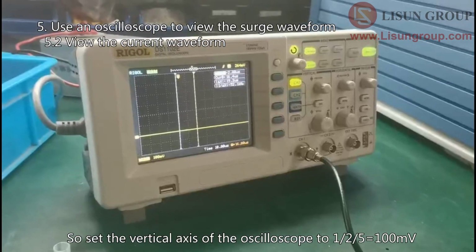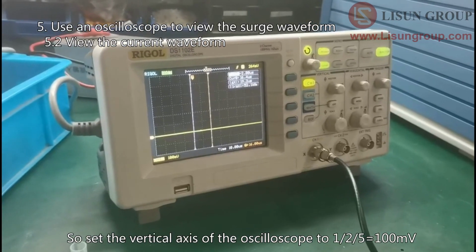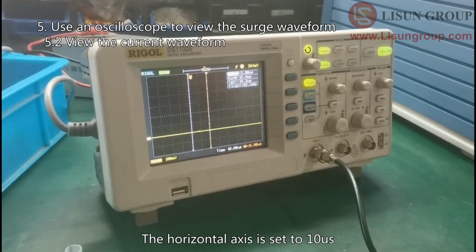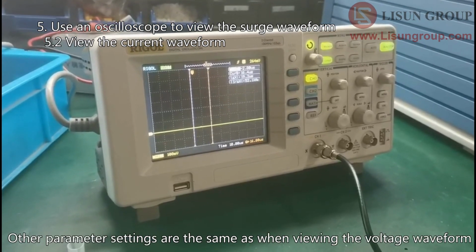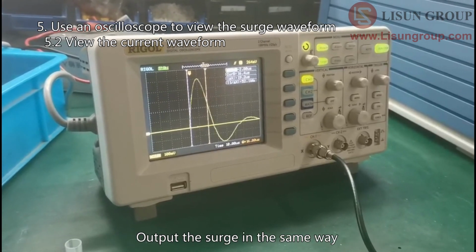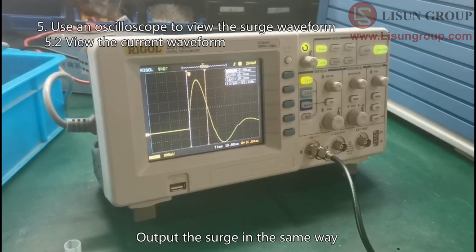So set the vertical axis of the oscilloscope to 100 mV. The horizontal axis is set to 10 microseconds. Other parameter settings are the same as when viewing the voltage waveform. Output the surge in the same way.